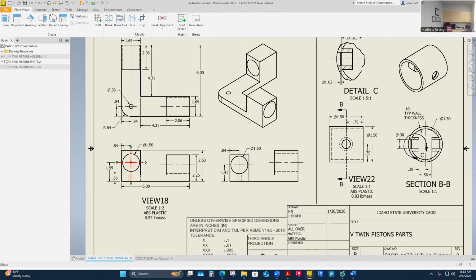That's one of the more critical dimensions here. Obviously, the heights were critical, the different heights, like this 1.59 versus this 1.41. Those are pretty critical heights too, because those connection rods have to be in plane, just off by their thicknesses from each other, so they can actuate those pistons. So those are critical dimensions. I definitely would recognize these as being really critical to the whole function, and this bore diameter.